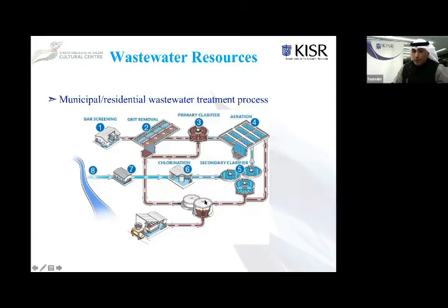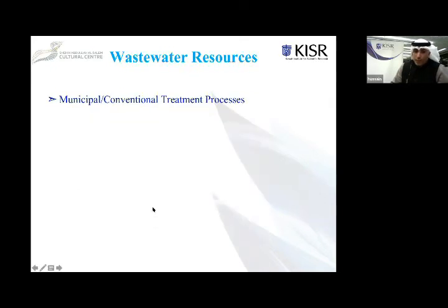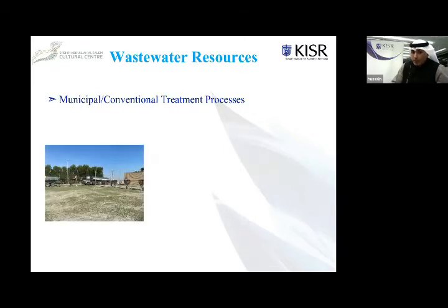For the lower tank here, we use two processes for the sludge produced in the treatment: either it is digested and returned back to the treatment plant, or we take it out as sludge and put it in a drying bed. The picture following here represents the treatment process that we discussed for the Al-Kabd wastewater treatment plant. The reception facilities, for those who are not connected, will bring the wastewater by tankers. Otherwise, other residential areas will be connected and pumped directly through the network to those plants.